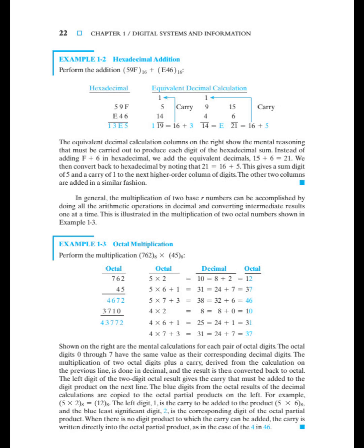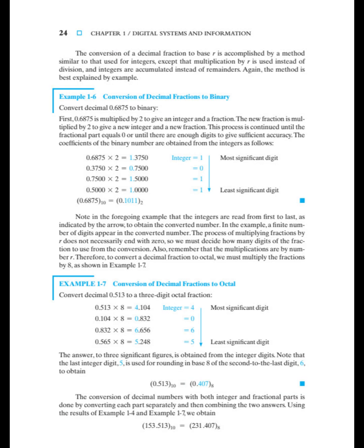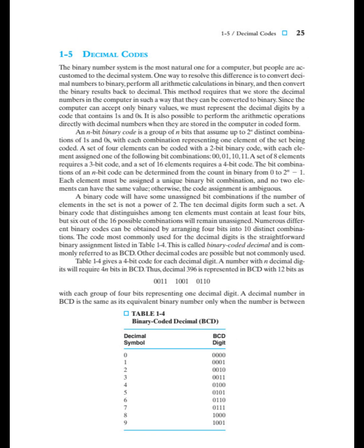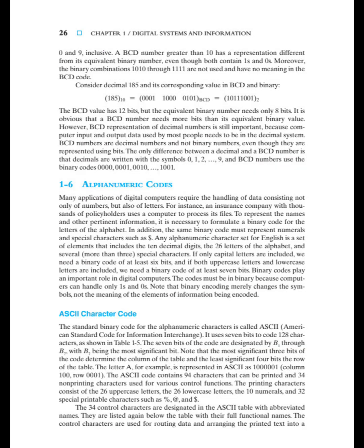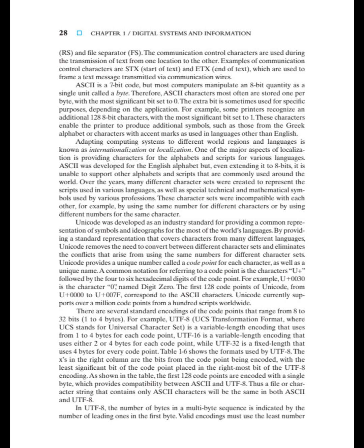By defining clear bands for high and low, we're building in a buffer against those little fluctuations, the noise, in electrical circuits. As long as the voltage is clearly in the high range or the low range, it doesn't matter the exact value. Exactly. It gets interpreted as a 0 or a 1 correctly. It's a wide margin for error. And for consistent operation, that's huge. It's like having two really big parking spaces. If your car is clearly in one or the other, there's no confusion.